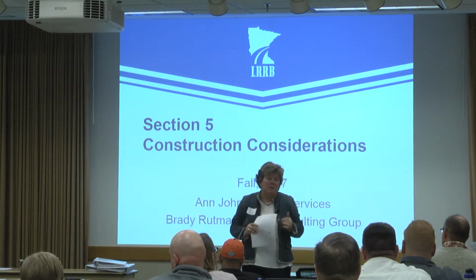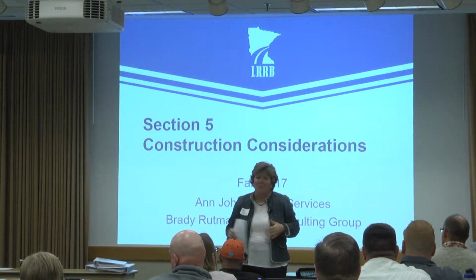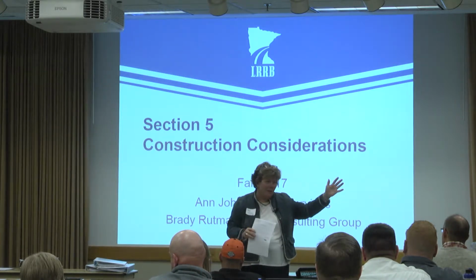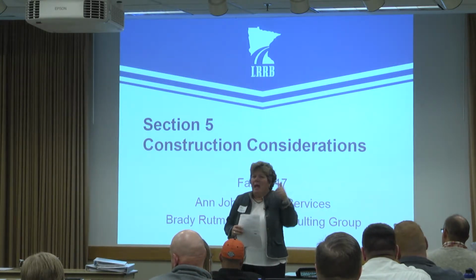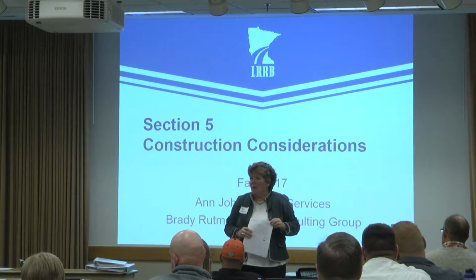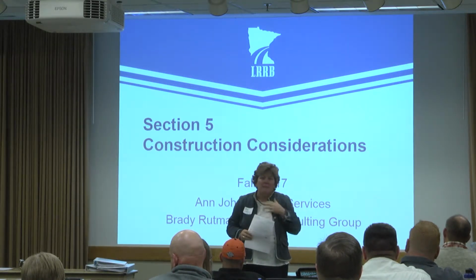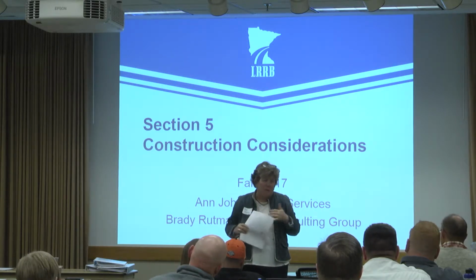Okay, so like I said, if you pay for removals and then concrete by the yard, you have more latitude because you can say, hey, just work with me, take out those 2 panels, you're going to get paid for it, right? And if you've done some surveying, you know that a few more panels is going to yield a better project. So that's me, not anybody else talking, but just me, okay?